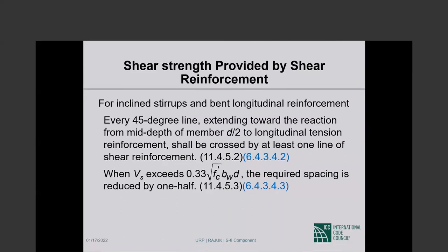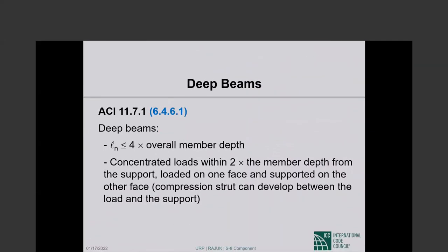This is the inclined bar stuff that I am going to skip. I will show you a numerical example, which will make things fall in place. I started from strength of materials, as you saw, trying to make the point that we are designing for diagonal tension, and then the concrete contribution to shear strength and the contribution of the shear reinforcement to shear strength. The concrete contribution has multiple parts: the shear in the compression concrete, the dowel shear, and the aggregate interlock shear, and all of that we lump together in typical applications.